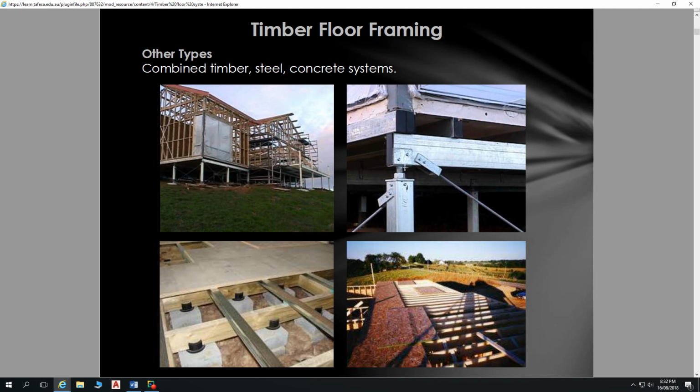And then if you've got deflection and things happening in your floor frame through settlement, from upheaval, etc., from soil movement over time, those can be adjusted and brought to level, because at times you do have settling of sites over time. You've got that ability. With your standard timber frame on concrete blocks, stumps like that, you don't have that capacity for adjustment. What's happening with the ground happens with your floor as well.